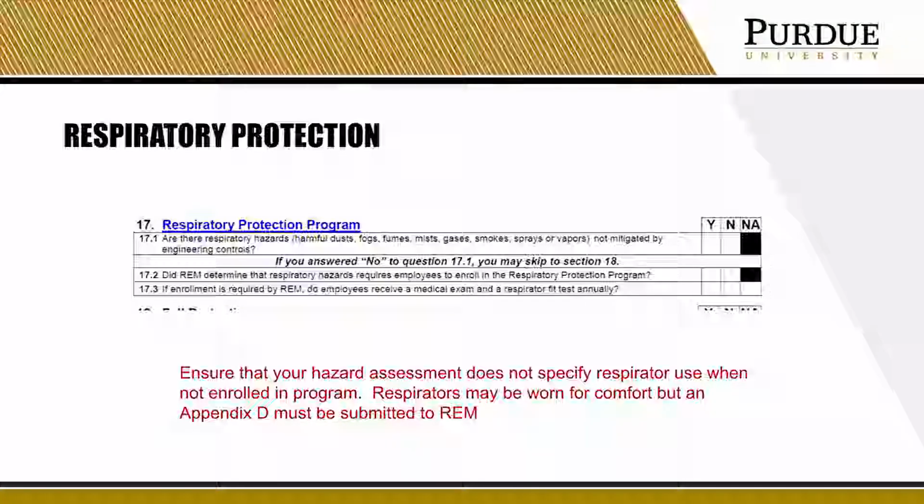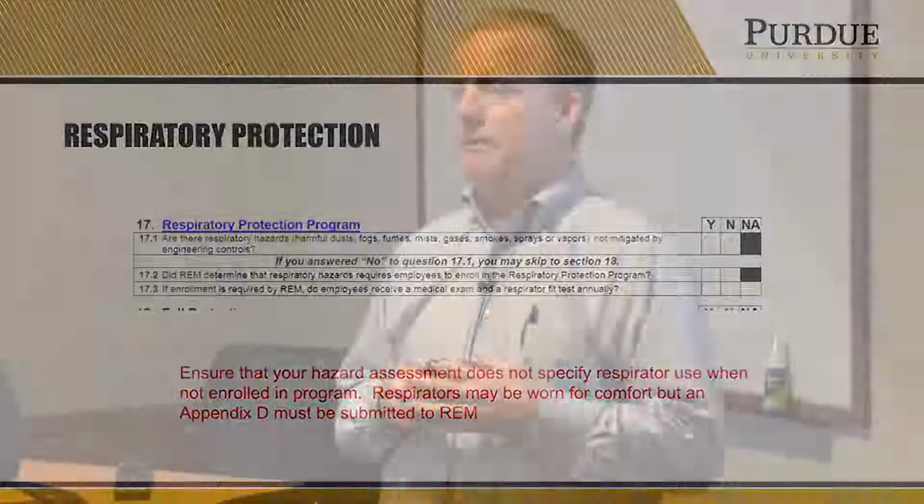Respirators. Again, another area that some people decide, well, you know, I'm working with the stuff and I'm going to wear a respirator. Well, that's fine, but there, again, through OSHA, there's a number of requirements regarding the use of respirators. So the question is, are there these respiratory hazards in the laboratory? And if the answer is yes, then what we want to do is help you evaluate that laboratory and determine, are you required to wear a respirator? We obviously would prefer that you work in a fume hood or something like that to prevent people needing to wear a respirator.